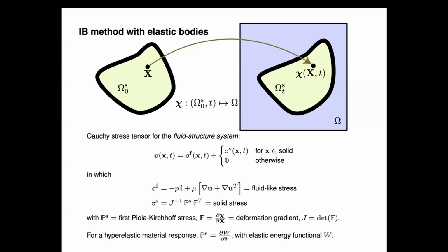So we've got, say, reference coordinates. These could be the coordinates of the structural body at time 0, or it could be some kind of virtual reference configuration that you never actually achieve. It doesn't really matter, but you've got some kind of material coordinate system, a physical coordinate system that you're mapping into current coordinates with this deformation map chi. And to understand what the model does, we need to talk a little bit about what the stresses